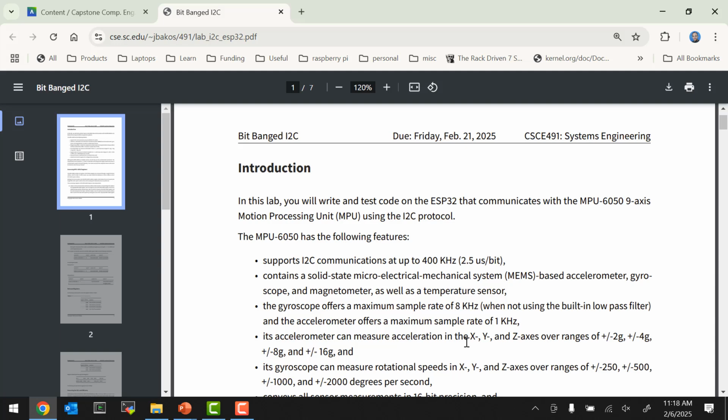Now, if you want to compensate for movement, there are also ways that you can include the gyroscope measurement, but we're not going to do that. Maybe next time. Other people have used the magnetometer to measure tilt because it's basically a compass. You can measure the magnetic force along the 3 axes to also measure that. However, if anyone holds a magnet up next to the sensor, then it fails miserably. Holding your phone next to it will mess it up. Any kind of magnetic field will disrupt it. So all of these approaches have downsides, but that's the goal.